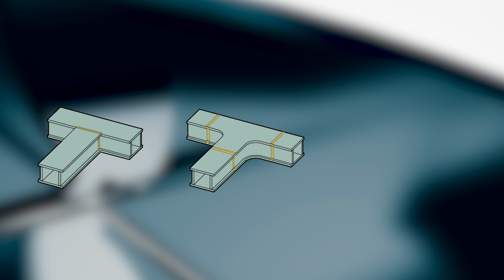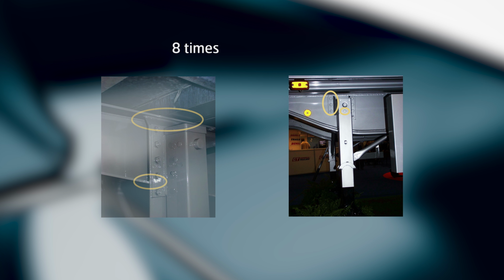In dynamic loads, the challenges are often related to joints. The pathway to increased performance is to refine, replace or remove these joints. In this application, you see the weld going all the way up to the area of the beam where you have the highest stress. If you instead move the weld to the center of the beam, you will have 8 times better fatigue life.